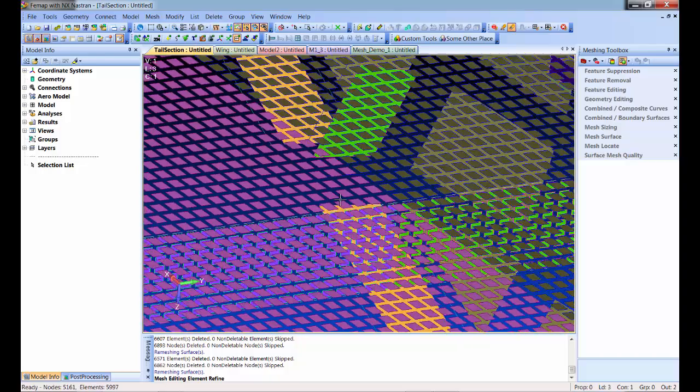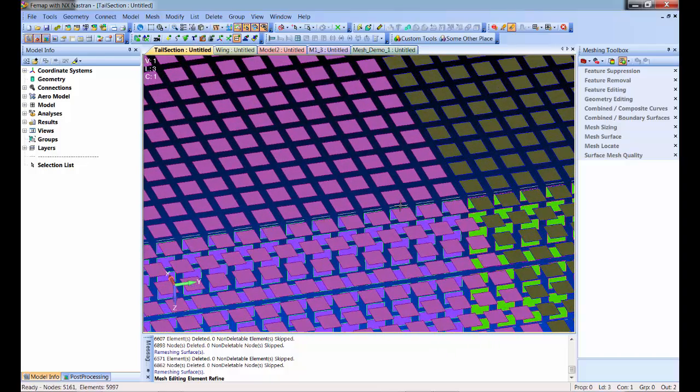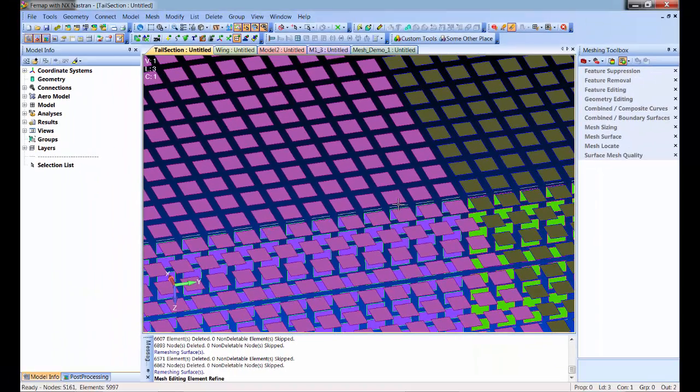There were beam little stiffeners around this model. It's splitting every stiffener. It's propagating pressure loads. It's propagating, like you got a laminate definition, the material angle for the split elements matches the one that was the original element. Constraints, if there was a constraint between the two nodes and they're same, it would put a new one in the middle node. So you can now pretty much refine meshes instantaneously.